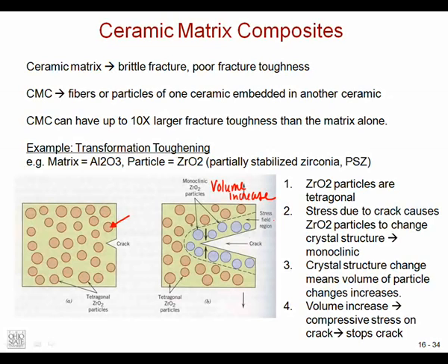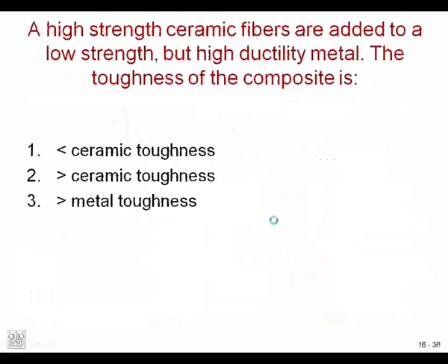But of course, they couldn't do that before because within these engine components, they need a long life. They don't want to have to replace them. They're never going to replace them. And so previously, the fracture and the compressive behavior of the ceramics, the low fracture toughness, would keep us from being able to use them.